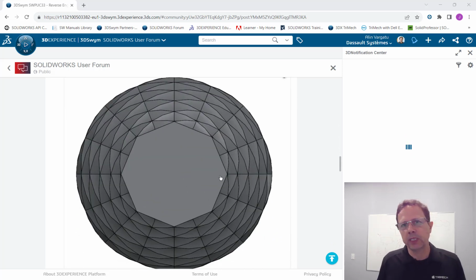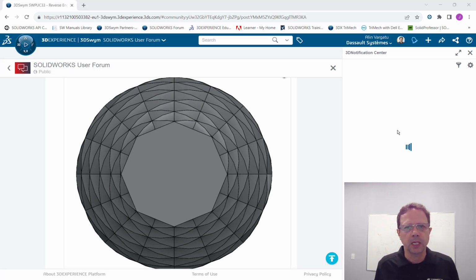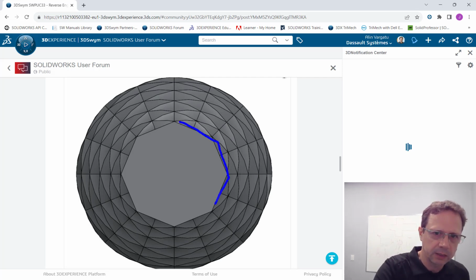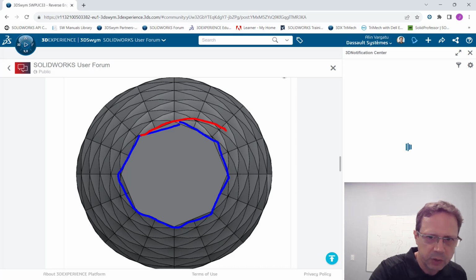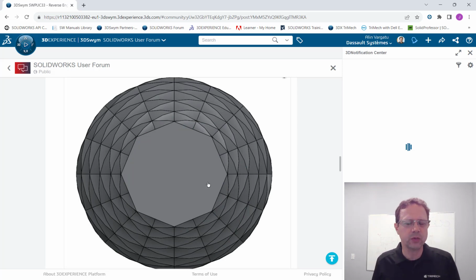And probably the most important picture, the one that would provide the best clue on how to do this the easiest way, is the bottom picture. So probably notice here you have a polygon, which makes things so much easier, right? If you're looking at the shape that we have on the bottom, it's a polygon, and this polygon seems to be swept. So if you pick up any of these points, it's being swept on something that looks like a variable helix. So that should have provided the idea about how to do it the easiest way possible.